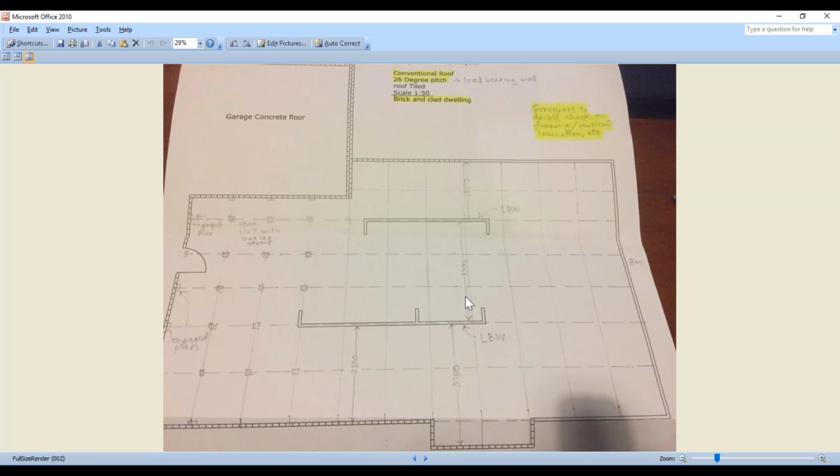So looking at Subit's measurements here, because we've got one drawn just here and one there under those load-bearing walls, the space in between those is actually 3.3 meters. So if we wanted to, we could have run one straight down the middle, but then they would have been at 1650, the spacing between the two, and there's nothing wrong with that. But what Subit has chosen to do is try and keep it under 1500 millimeters, and therefore he's put two rows in there. So now that'd be at 1100 millimeters. So that one there would be 1100, that would be 2.2, and then 3.3 to the next one. So that's what he's done.